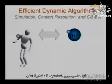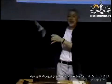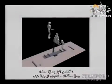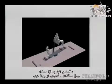But in here, we are going to be able to reduce the problem to this, because we can use the mass matrix in this direction. We can use the effective inertia directly. The collision doesn't care about what humanoid robot you have. You just need to know what mass properties you have at the contact.